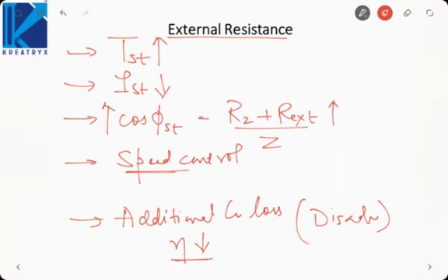So wound rotor is more flexible as compared to squirrel cage. But the thing is, squirrel cage construction is very rigid, so it is less damaged. Okay, in any condition it can be used. The damage or the wear and tear is very less in case of squirrel cage. It is a rigid construction of the machine. One of the advantages of squirrel cage is the rigid construction. It is not easily damaged, because the winding is not actually a winding, it is the conductor bars.